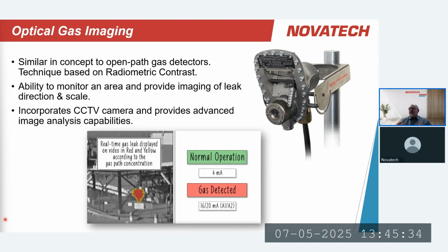The way these work is basically, as opposed to having a detector and a receiver where we're looking for infrared absorption, we are now effectively looking at disruption of thermal, or basically radiometric, signals. So surfaces that have a certain temperature, when a leak occurs, will have a very rapid change in radiometric behavior or emissions.